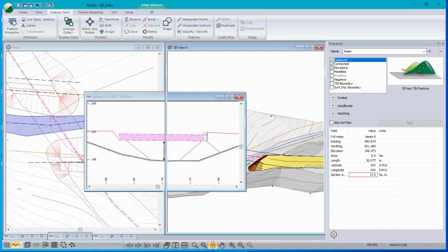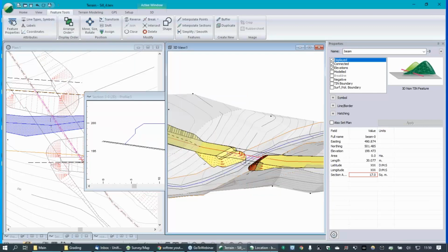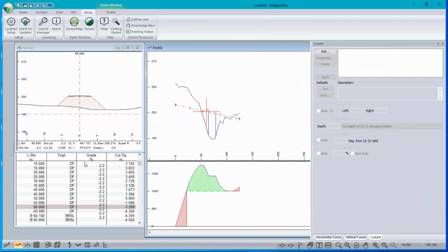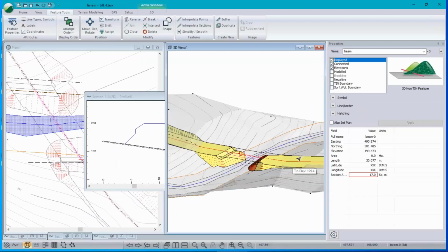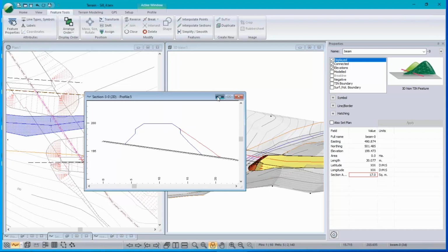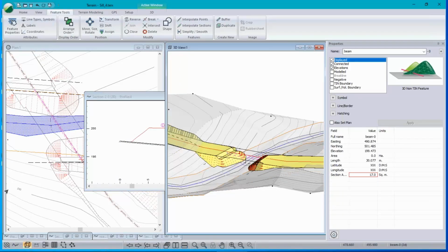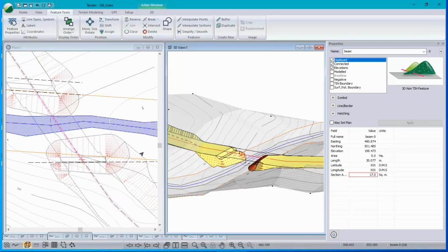You can generate a table of offsets to any point code at any cross section. In the terrain module, what you would do is either draw a feature and generate lengths and therefore offsets, or, and I think this might be better, just generate some points, some XYZ points.